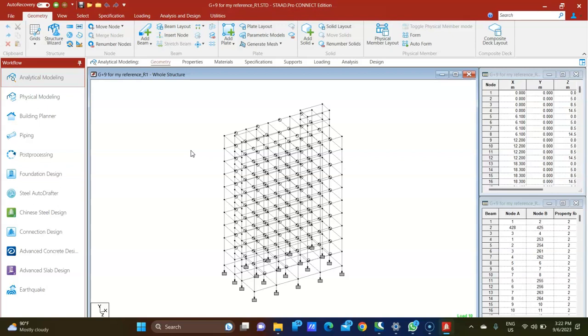After design, if you see the column reinforcement is coming at 0.5%, 0.8% is the minimum you provide. So it means there is a chance the section can be reduced. As a result, the percentage of reinforcement will increase.